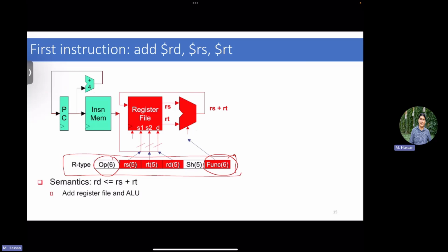This is basically your write port for the register file. So these are your 2 read ports of the register file, because you need to read 2 registers to execute the addition. And once you obtain the result, you go ahead and write it back to the register file. Good. So this is simply your decode and execution stage.